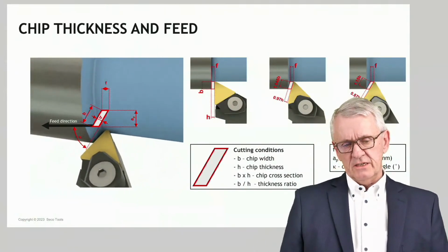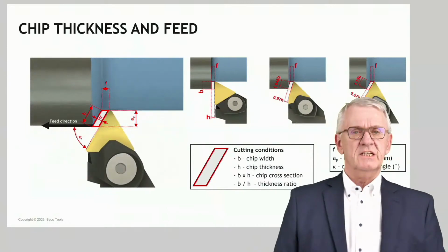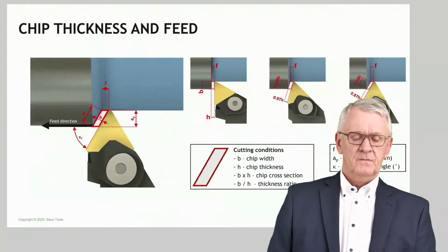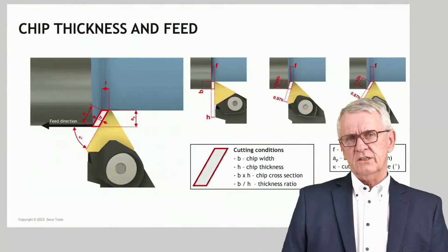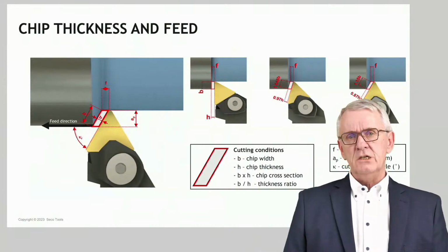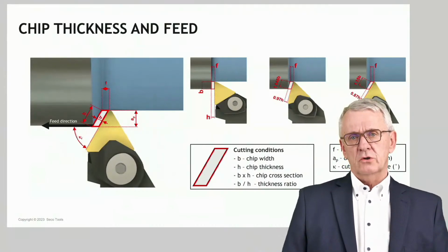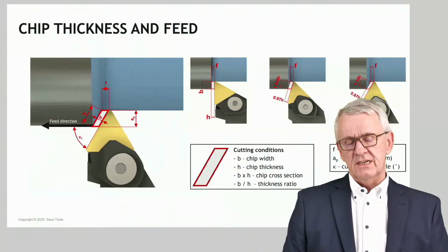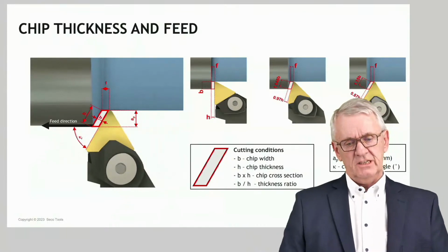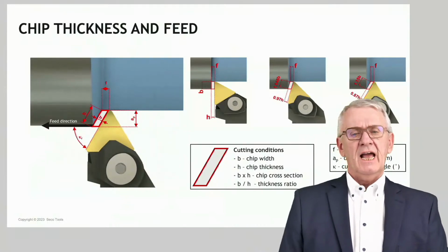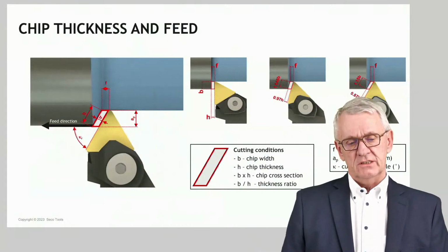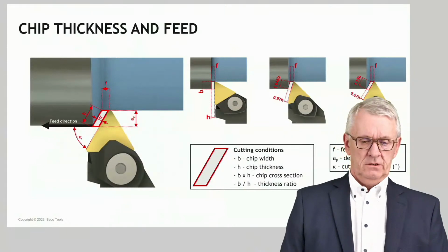We were talking about cutting conditions, workshop cutting conditions, technological cutting conditions. Workshop cutting conditions are the cutting conditions that we use in the workshop, that we use to program the CNC machine. Its depth of cut, its feed, and its cutting speed. And traditionally, these things are fixed.